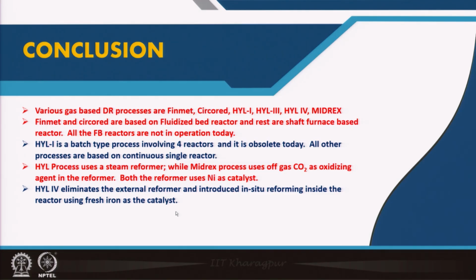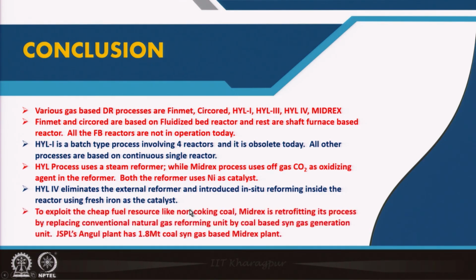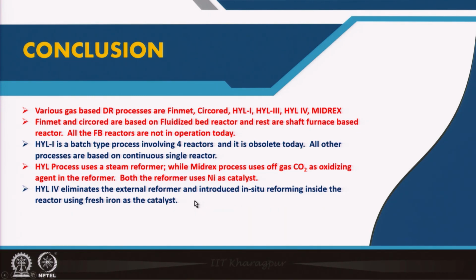You don't have to bear the cost of the catalyst and also its replacement. Here you have nascent iron inside the reactor and that acts as a catalyst. Also from the energy point of view, since you don't have any external reformer, you can save a lot of energy.